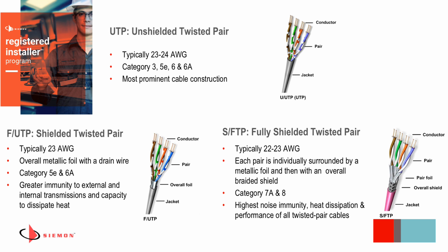There's not a lot of Category 6 level cabling necessarily, but the benefit of the shielding is that it has the ability to reduce exposure to and radiation of external and internal transmissions, but also has the ability to better dissipate heat for remote powering types of applications, which is why shielded cabling is recommended for support of things like power over Ethernet types of applications.